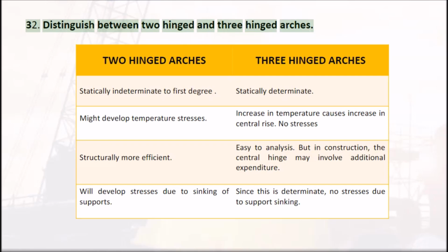Distinguish between 2-hinged and 3-hinged arches. 2-hinged arches: statically indeterminate to first degree. Might develop temperature stresses. Increase in temperature causes increase in central rise.